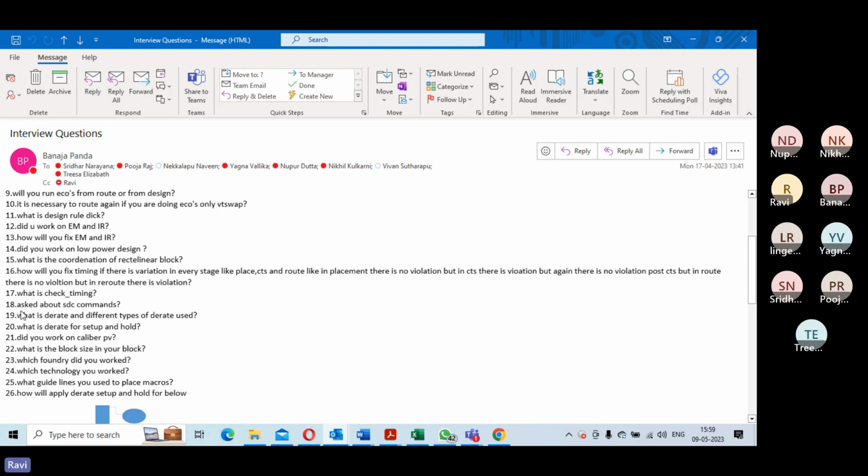In reality, for the contribution of IR drop during launch versus capture when doing setup analysis, during capture there could be more current drawn. So theoretically, the IR drop at launch and capture on the same cell may not be the same.